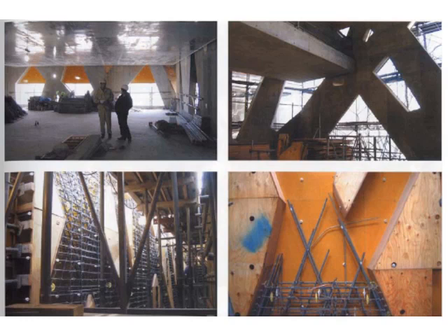This is the inverse of one of those shapes. Notice we've got solid pieces here and here that are representing the voids. That's where the windows are going to end up going. And look at the nest of rebar that's inside this. This is not little tiny rebar. I would say the smallest rebar in here is probably number 6, number 7, something like that. This is big, big rebar.